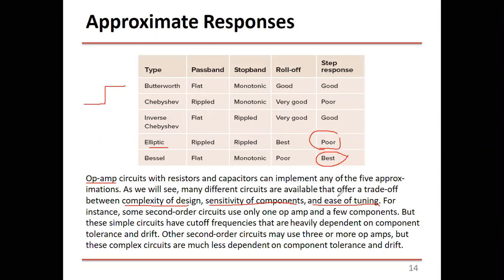Okay. The third point, is it easy to tune? Like if you design a filter at 1 kilohertz, and I told you, okay, no, I'm sorry, my calculations were wrong, and I need to retune it at 2 kilohertz. Is it easy? Do you just replace one resistor or one capacitor with another value and that's it? Or you need to change the whole design? So these are the 3 parameters or points that you evaluate the goodness of a filter design based on.